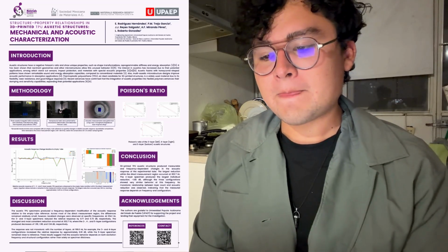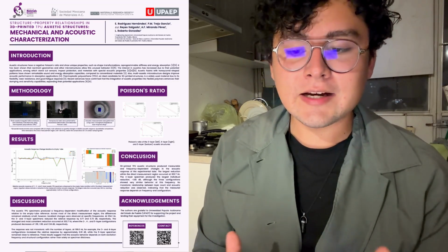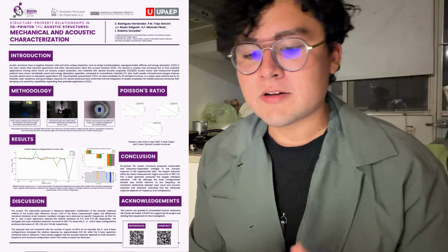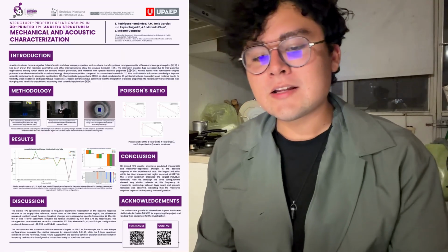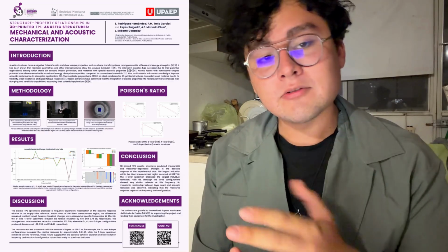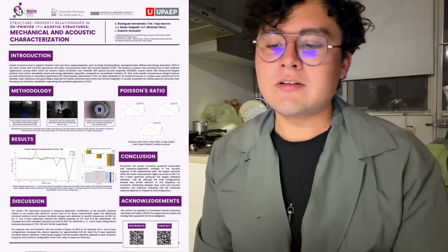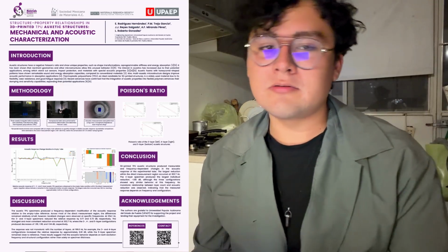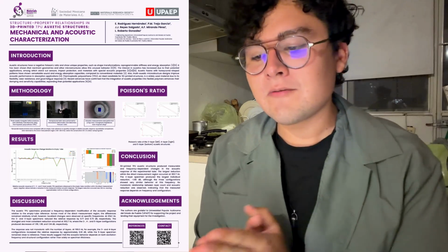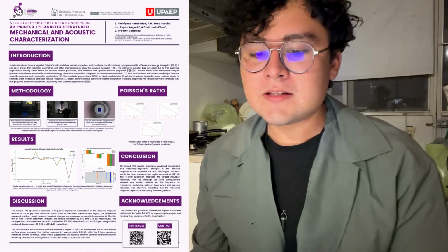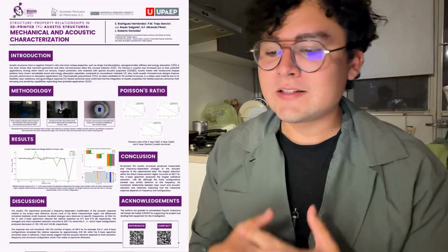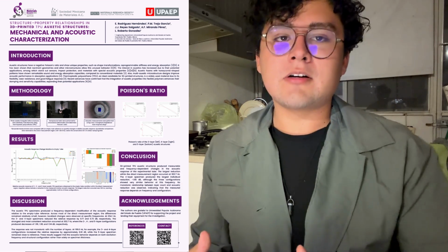However, an interesting result is that adding more layers did not necessarily produce a greater acoustic reduction. For example, at approximately 169 Hz, the 3 and 4 layer structures increased the response by around 0.71 decibels, while the 5 layer structure remained closer to the reference. So we did not observe a monotonic relationship between the number of layers and the acoustic response. This suggests that the behavior is not controlled only by specimen thickness or layer count, but rather by the interaction between the excitation frequency and the structural configuration.